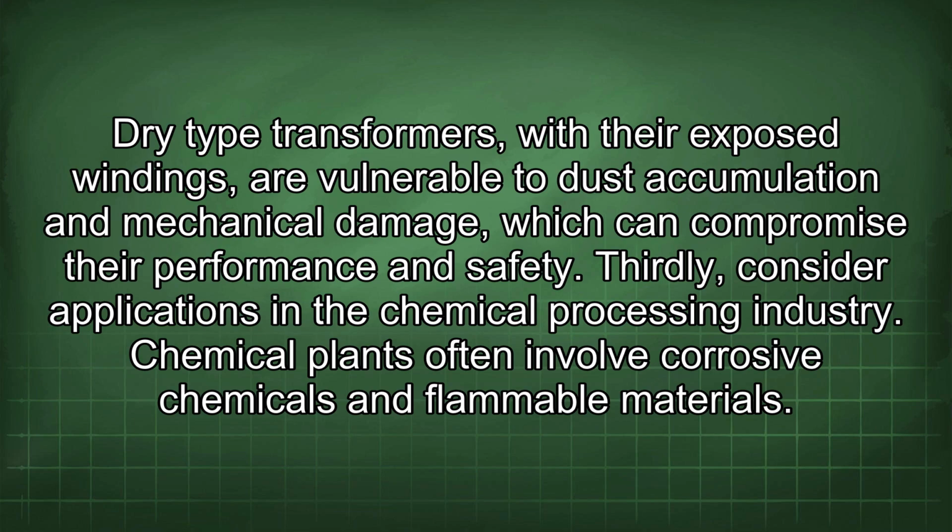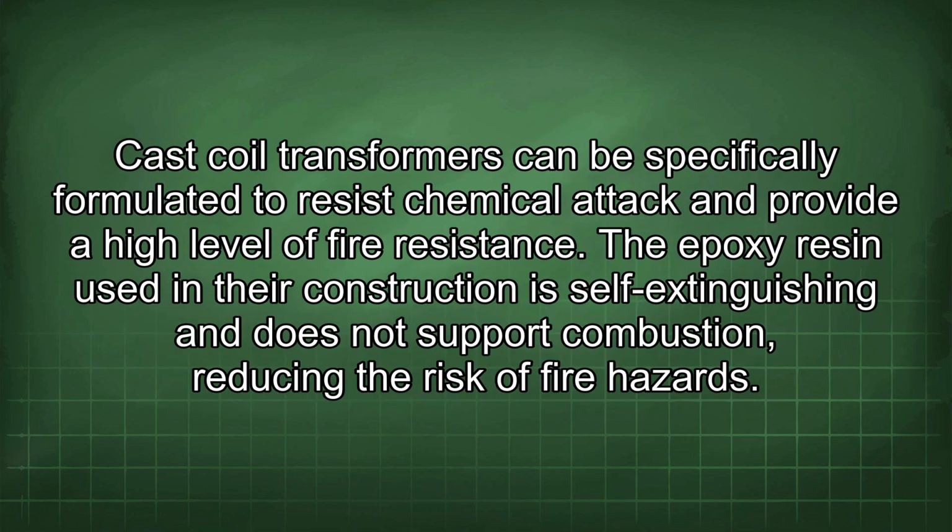Thirdly, consider applications in the chemical processing industry. Chemical plants often involve corrosive chemicals and flammable materials. Cast coil transformers can be specifically formulated to resist chemical attack and provide a high level of fire resistance. The epoxy resin used in their construction is self-extinguishing and does not support combustion, reducing the risk of fire hazards.